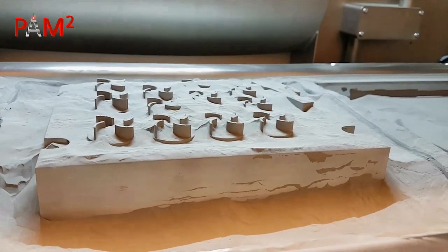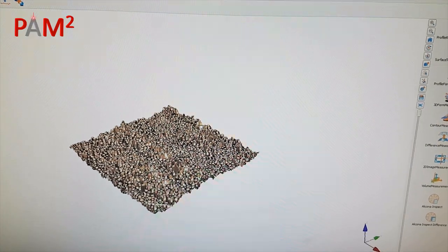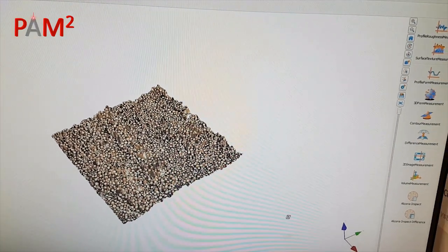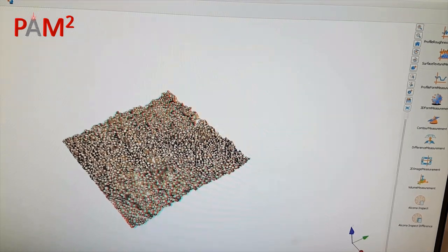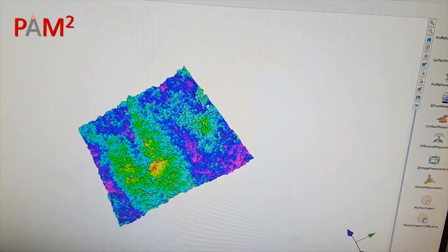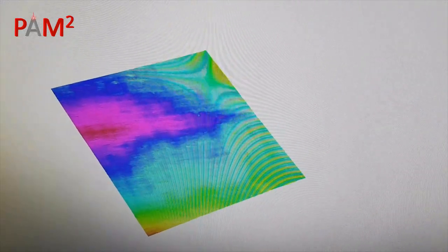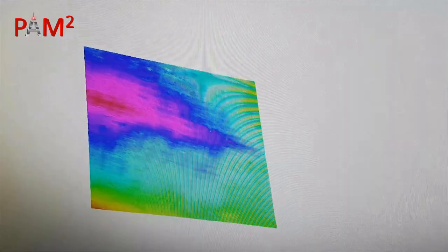quality is required. The parts produced by the SLM process typically have a low surface quality, mainly because of the interaction between the tracks and projections of metal droplets from the melt pool. To reduce their surface roughness, they usually need to be post-processed, most often with machining tools or laser.